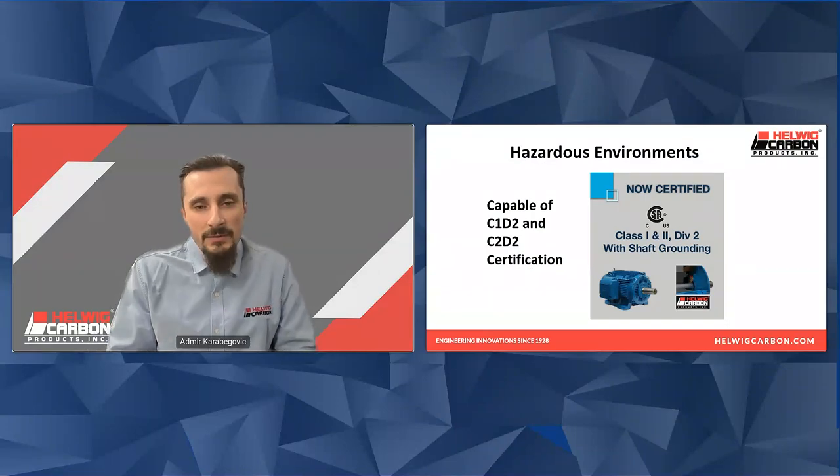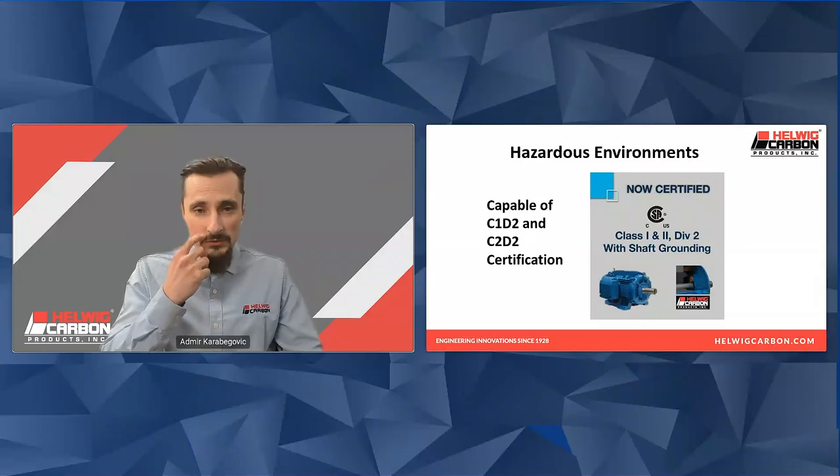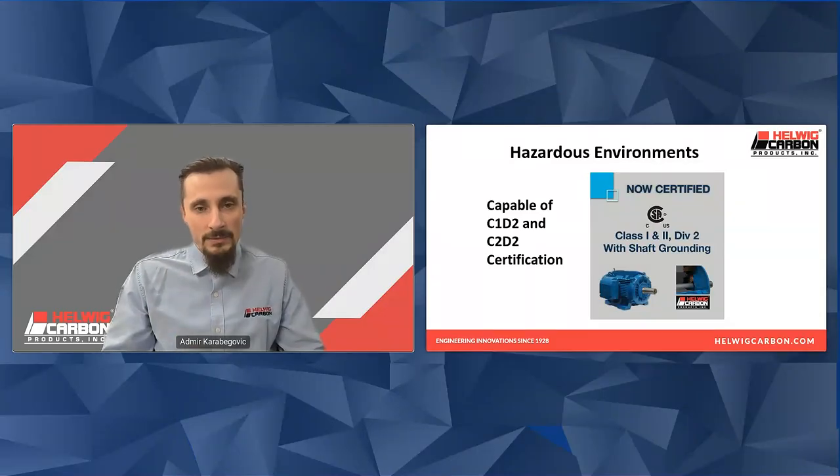So, hazardous environments. There are applications out there where these kits need to be capable of C1D2 and C2D2 certifications. If you are operating in such an environment, what I would recommend is to go back to the motor OEM and tell them that you want to equip the equipment with a bearing protection kit device. We have gotten certification through an OEM. Hellwig does not provide this certification.